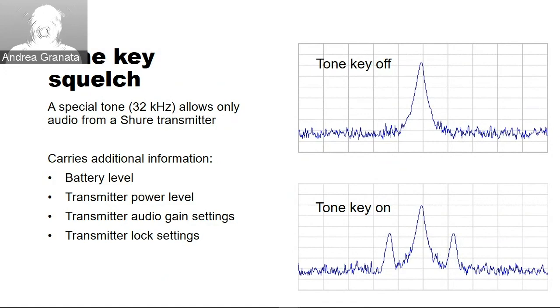So the squelch helps you have silent operation when switching on and off, as much as it helps you prevent noises. For example, when we switch off a transmitter, we would have pure RF noise decoded and sent to the audio output. The squelch interrupts the signal and makes sure that your audio output, when your transmitter is off, will be muted.